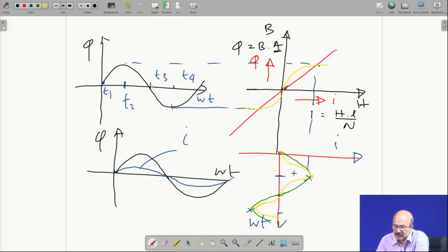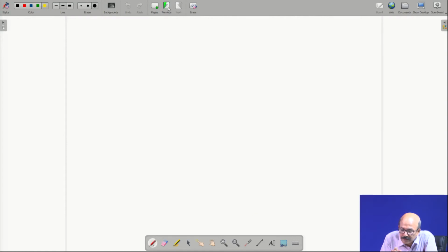If you split this into different harmonics, you will see you have a fundamental and a predominant third harmonic. Let us neglect the third harmonic part. So, still the fundamental will be in phase. We are fine with that, with these simplifications. So, we still say that with this kind of nonlinearity introduced, your current will be in phase. What happens when we consider hysteresis? Quickly let us go to the next page.